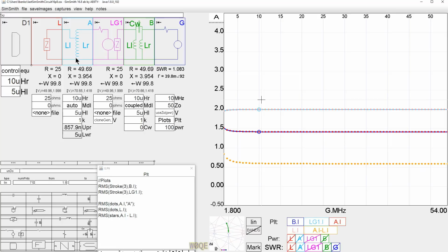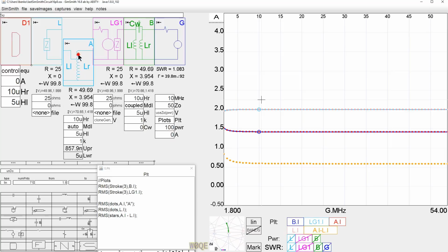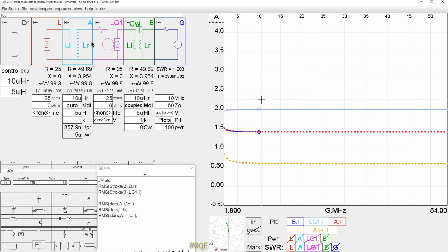Now, you might not want to care about that for a very small transformer, but if this was a transformer that was trying to handle 1,000 watts, having the ability to have 70% of the turns be a significantly smaller wire gauge might be advantageous to you. That's point one, as far as, we had the isolation as being a plus for this transformer. Now we have the ability to use a smaller amount of copper to do the auto transformer. And this part of the winding right here has to, of course, match the same current that this winding has over here. So we don't save there, but that's only 30% of the turns.